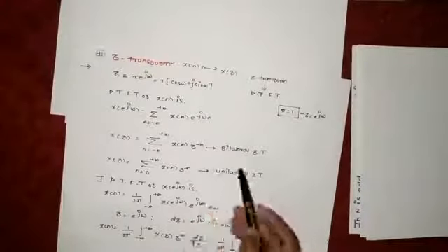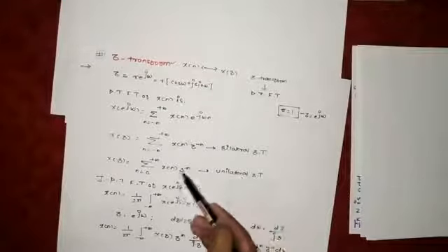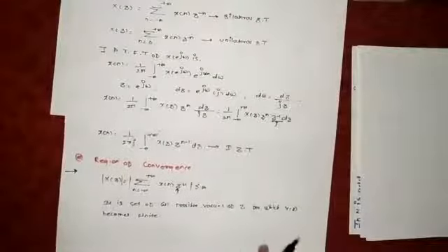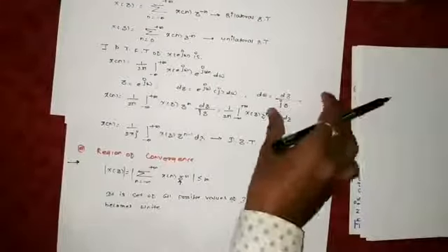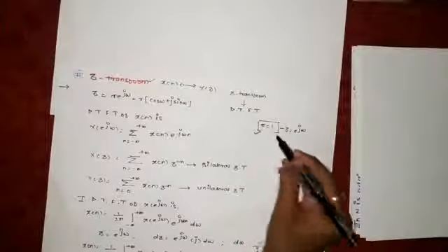Now as far as the possibilities are considered, by this equation we can have a transform for left sided as well as right sided sequences. For a right sided sequence it is greater than, and for a left sided sequence it should be less than, and based on that the region of convergence can be drawn for the Z transform with respect to a unit circle, because we are considering radius as 1.